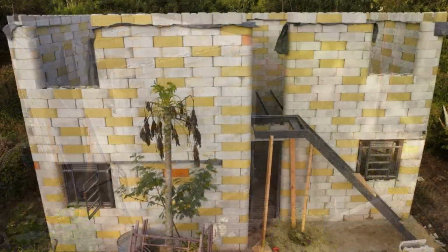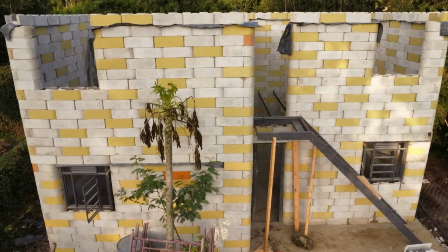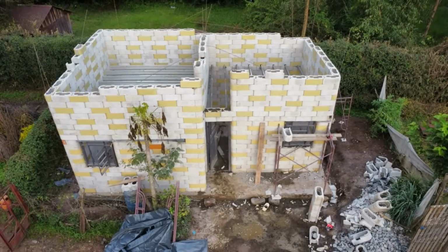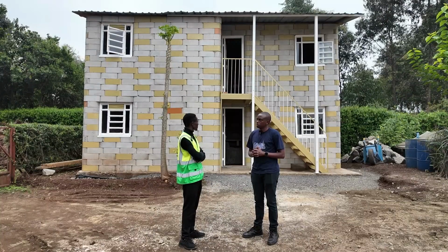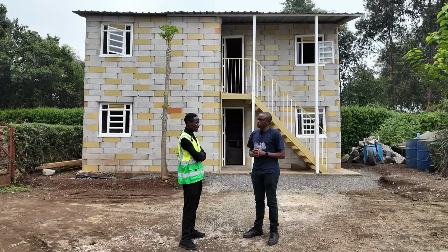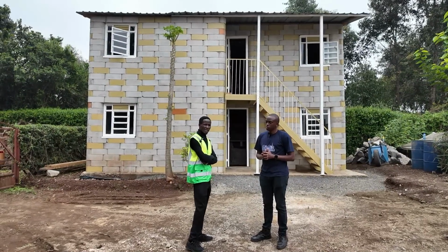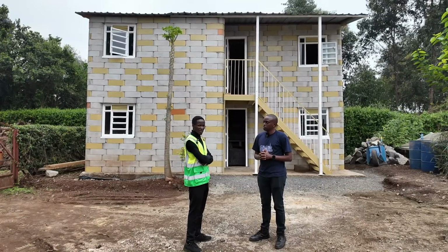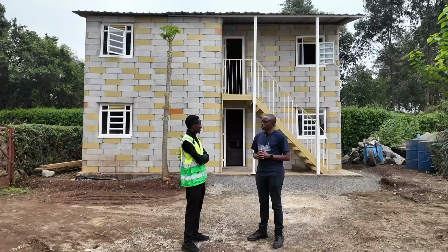Why do we do that? We do it to prevent horizontal forces, and also to distribute the loading properly within the structure. So we employ a method known as tension bars, steel reinforcement at the corners of the houses.